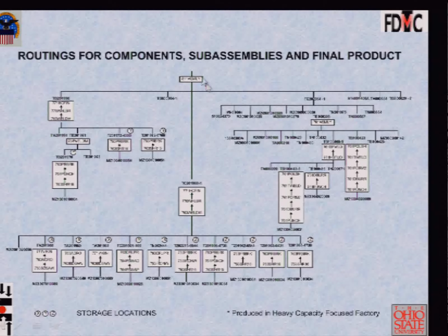So, this is what the indented bill of routings would look like. You know, there are three major sub-assemblies: 1, 2, and 3. Lots of purchase components, not very important. You know, these components could be delivered point of use by a tugger, or they could just be in racks or bins located equipment side. But this is the big thing, that try first and foremost to have three separate sub-assembly cells. Is that always possible? No. But asking why it's not possible is worth the company's effort.